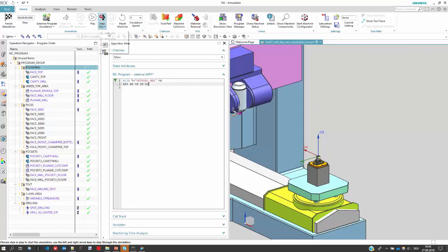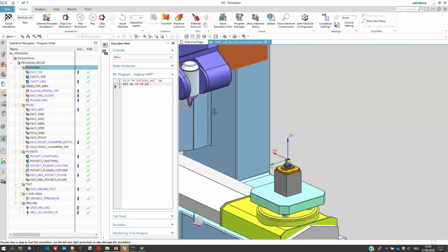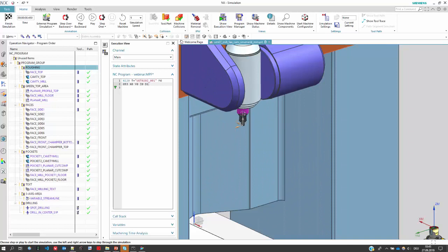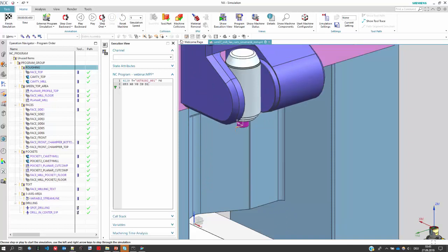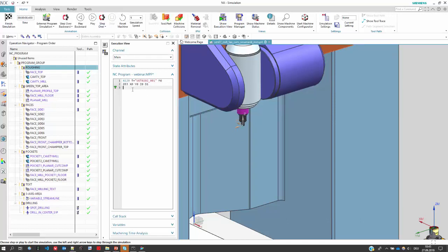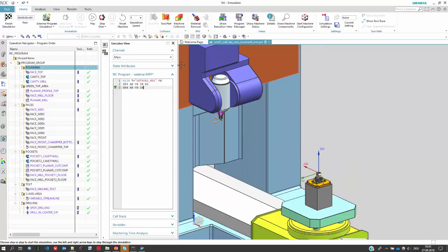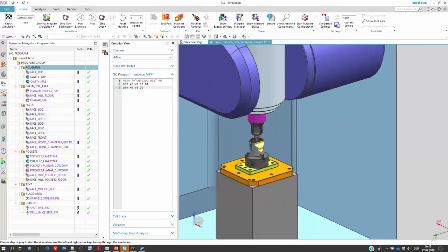And as you maybe can see, the tool jumps here, or the axis compensate now the tool length here. Let me do it again, maybe it was a bit too fast. So the tool gets mounted, and when I now move with the active tool length compensation to 0 position, it moves up. And the same is here for the G54. When we now move to our first local offset, I guess it is here at the top of the part, it should move to this position.